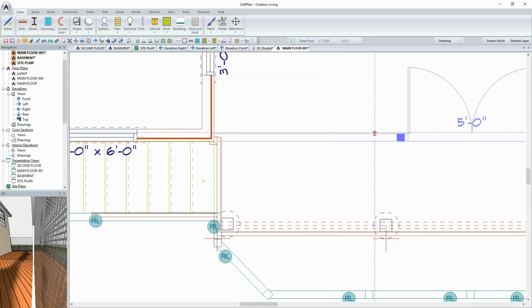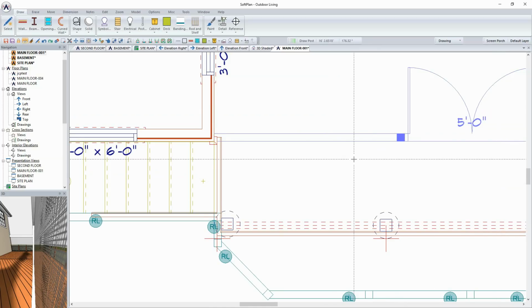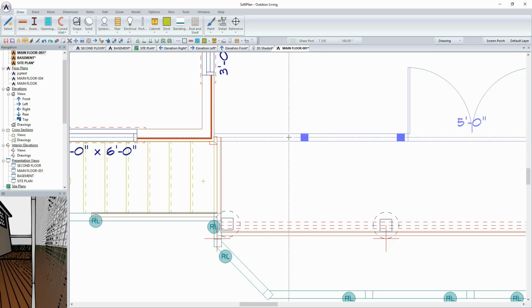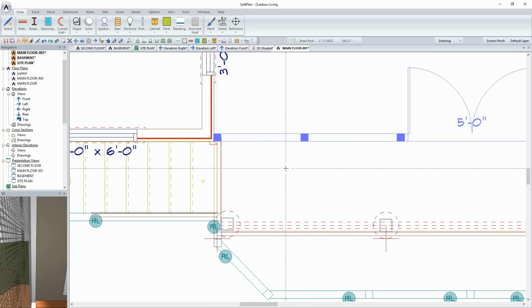And so with that information, I'm going to right click and select the post. With my snap feature on, once again enabled using the F11, I can see with the projection snap when I find the midpoint of the wall, and I can position my cursor where I wish to place this and click. And then I could add a secondary post over here to the left hand side.